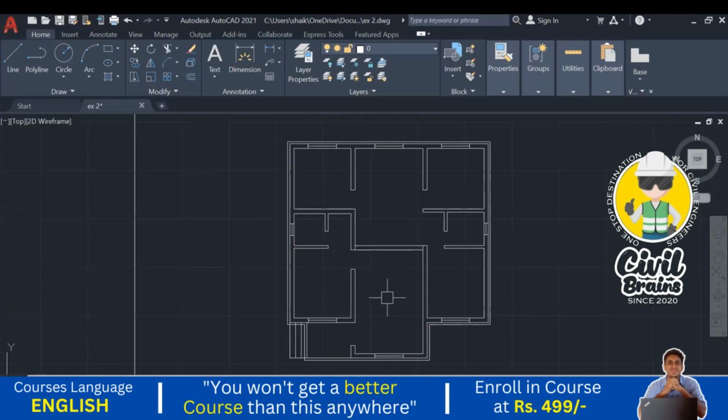Okay, I will quickly draw the slab projection. What is slab projection? From the face of the wall, how much it will come outside. Why do we need to provide the slab projection? To avoid dampness of the wall in the rainy season. Where heavy rains occur, we need to provide the slab projection so that the rainwater does not fall directly onto the wall. So there is less chance of dampness of the walls. For that purpose we are providing the slab projection.